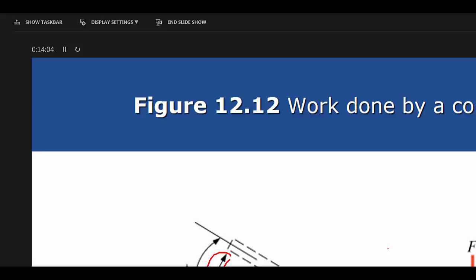Okay, then let's see on 12 there. On this one though, we're looking at diameter, right? Determine the required diameter. You're given that you've got a 1020 steel, transmit power of 50 kilowatts. Speed of the shaft will be 6 revolutions per second. The allowable shear stress is 67 megapascals.